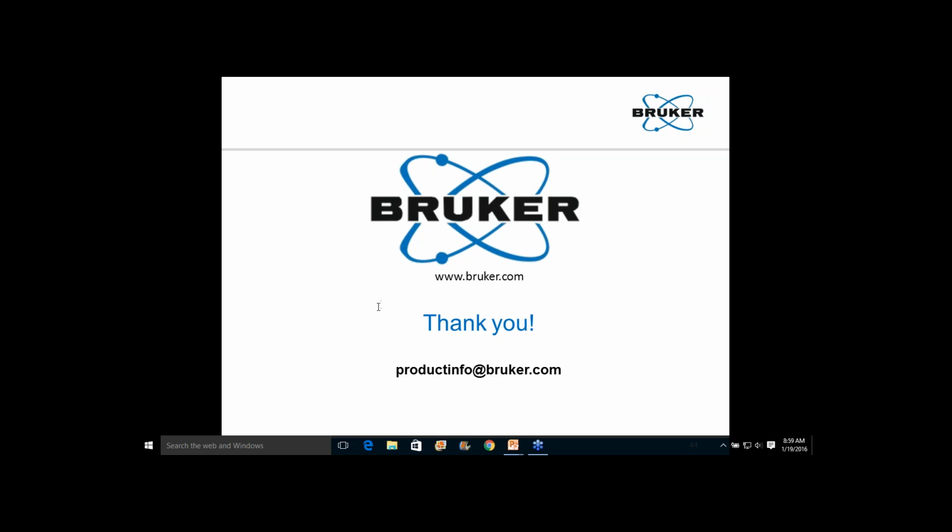There is another question. Probably I'll take this as the last one. What is the accuracy of the G encoder? Okay, accuracy is conservatively I'll say about 1 micron. It is maybe sub-micron, but 1 micron. So maybe if you are measuring about 10 micron, you will have probably 10% error in it. If it is more than, say, 20 micron, you'll have much less error using the G encoder.